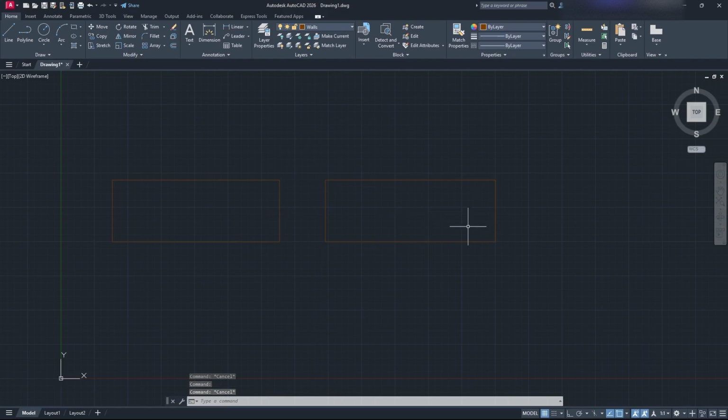For the most part, you're going to want to be using polylines for everything because it just makes things way easier. However, if you do lines and you do find that easier, then you can do that as well. If you're drawing lines and you want to just use lines but then make them polylines, what you can do is take your cursor and put it in the bottom right-hand corner of your drawing, or the top left-hand corner, or whatever. As long as you're going over all the lines in your drawing, it's fine.